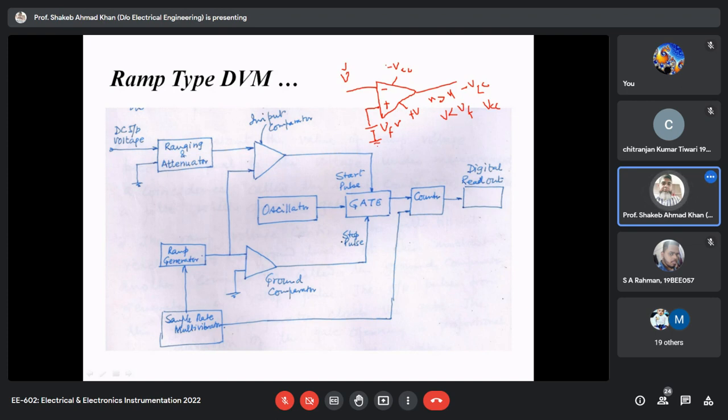Wherever in control circuits, automation circuits, or instrumentation circuits we require a switching application, we use it. Suppose we have a temperature sensor, and we want to switch on the heater when the temperature is less than a certain value, and switch it off when it is more.